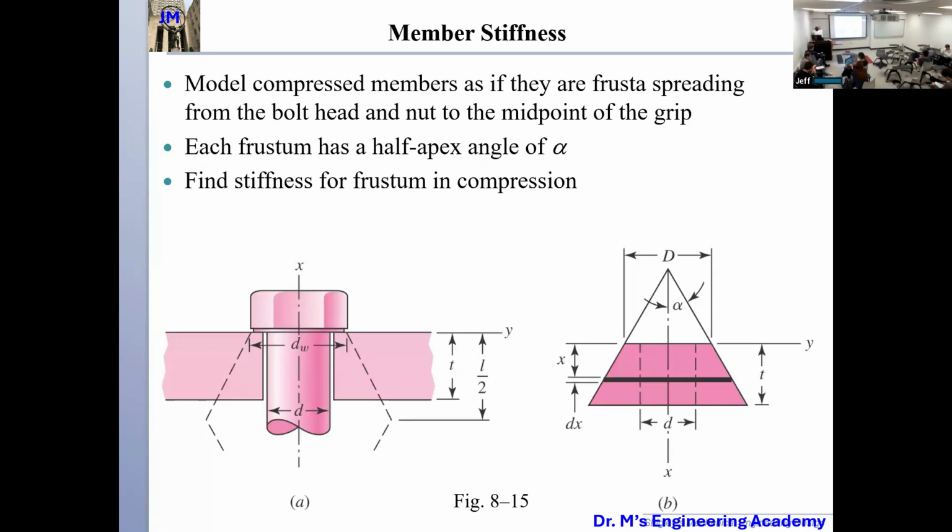For this dx, the dx is the length. So we know that d delta equals epsilon multiplied by my original x. You understand, guys? This is the deflection of my dx. Here you can see this is an infinitesimally small segment.